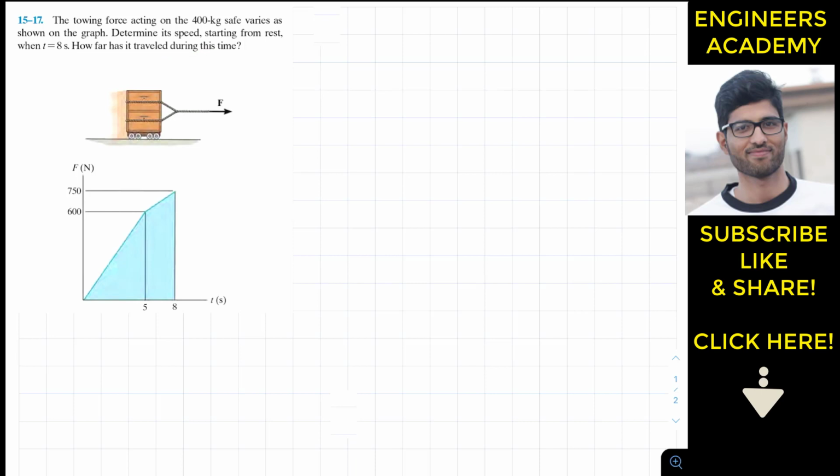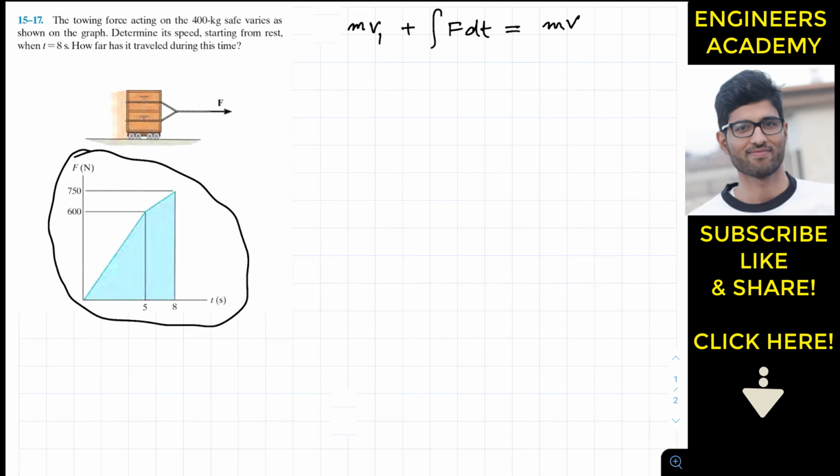For that we have to apply the principle of linear momentum, which says that the initial momentum plus the impulse due to the external forces will be equal to the final momentum, and let's say that the final velocity is v. We can see that the force is given as a function of time, and we have two intervals.